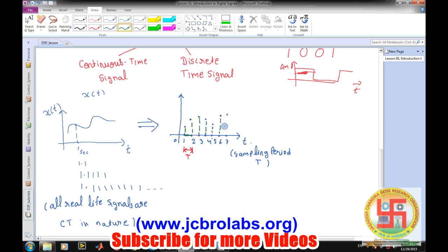Still, it comes into the analog category because the amplitude can still have any value. It could be 1.1 or 1 point something, or say 2.5, 2.6, any value. But on the time axis we have discretized it. That means it can have only specific numbers. So now we represent these as x(nT), or x[n]. Right, so these are the discrete time signals, and now coming to digital signals.